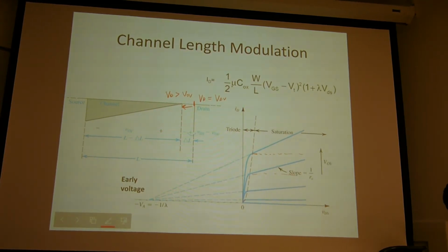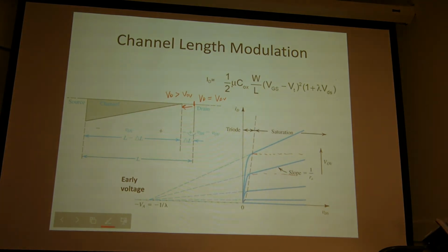In the band model, we describe this as the lowering of the barrier top towards the source side. They are equivalent ways to describe the current further increasing with the drain voltage, but from different physical pictures. So you're describing the same thing in two different models. Yes, in one the channel length is effectively lower, and the second case says the band is lower.